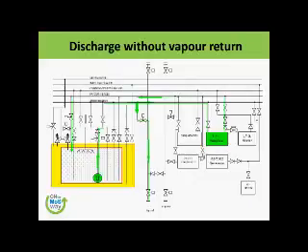We discharge the cargo through our liquid header and take the vapor from shore. If the shore is not able to give us the vapor, we will have to give part of the liquid to our vaporizer, and from the vaporizer we will be able to make our own vapor and throw it in the tank.